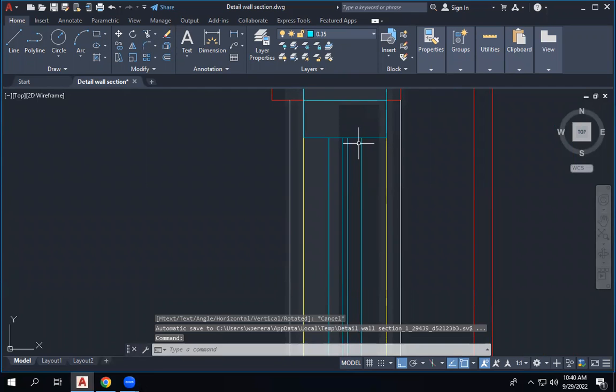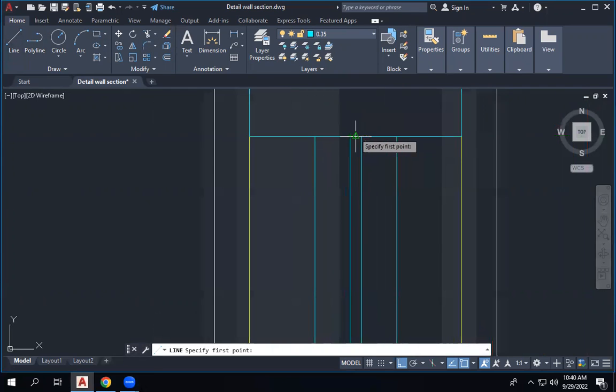So you did the 1/8 and then you offset it. Yeah, what I did is this is the center line. So I just offset 1/8 onto this side and 1/8 onto this side. And after that one, I offset 3/4 from this and another 3/4 onto the other side.